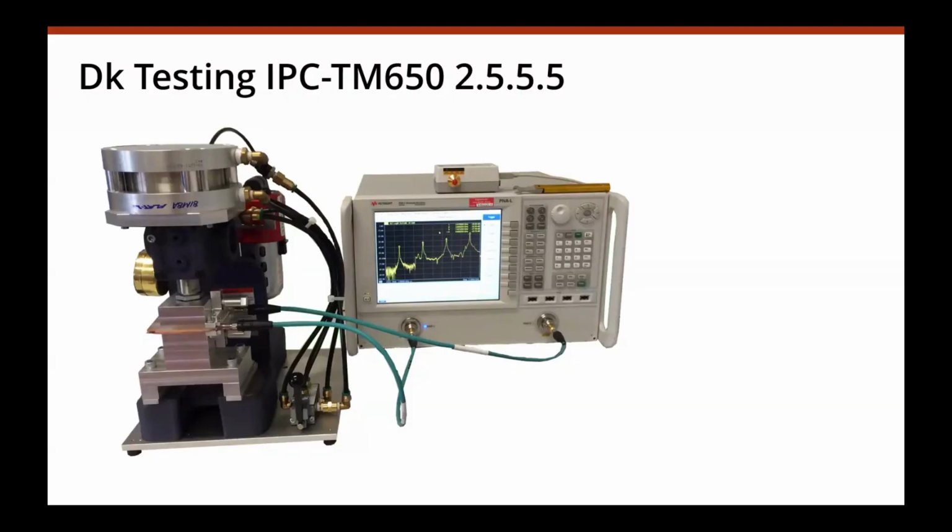So what you have is a resonant structure, and you get peaks in your transmission at certain frequencies that are shown by those peaks. And by measuring the frequency of these peaks, you can back calculate the Dk of your base material. This is one of the standard methods in Dk testing for base materials as shown in the IPC test manual. It has quite a number of limitations, but it's still the one that is quite easy to conduct on the side of a laminator, and it gives you a good indication of Dk.